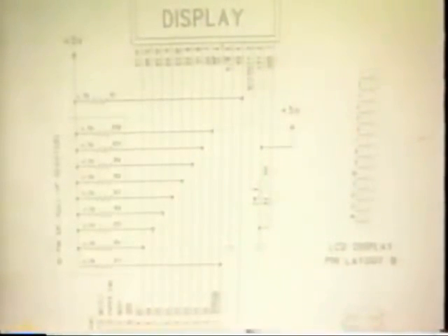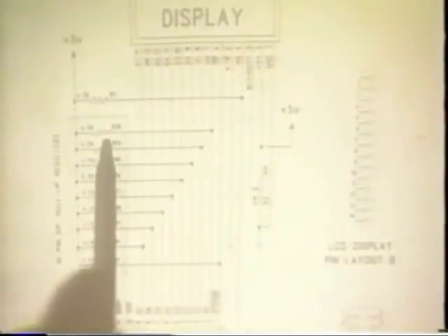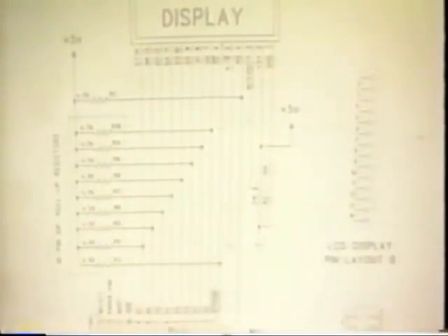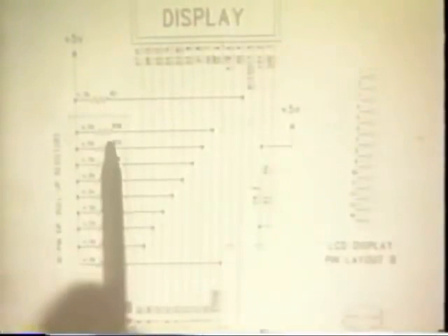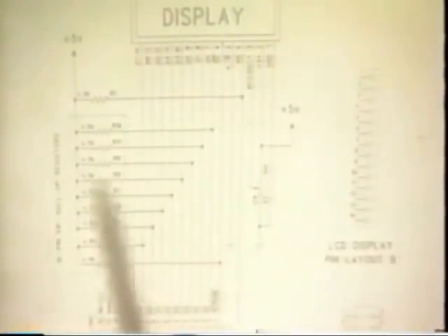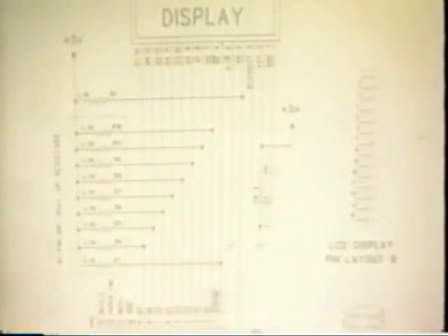And does anyone know why you use, this is called a pull-up resistor. Does anyone know why you use pull-up resistors? Anybody at all? What do they do? Yes, sir. It would be Harold. Yes, Harold, why? Yes, it makes a bigger, cleaner signal. If the wire from your computer to your display is over about 6 inches, this makes it a much cleaner signal. So we're going from 5 volts to ground instead of from 5 volts to 2.5 volts, right? Yes, exactly. The signal-to-noise ratio is less.